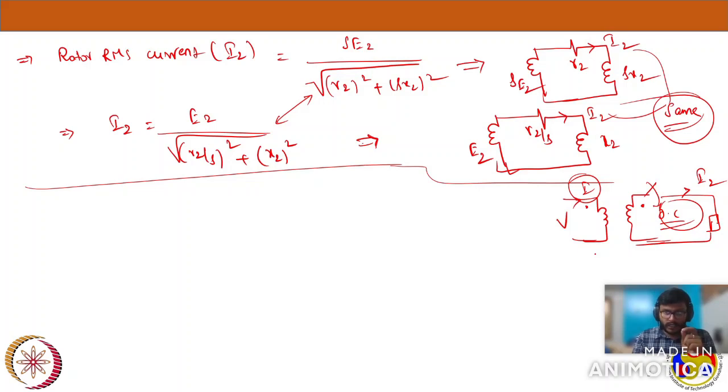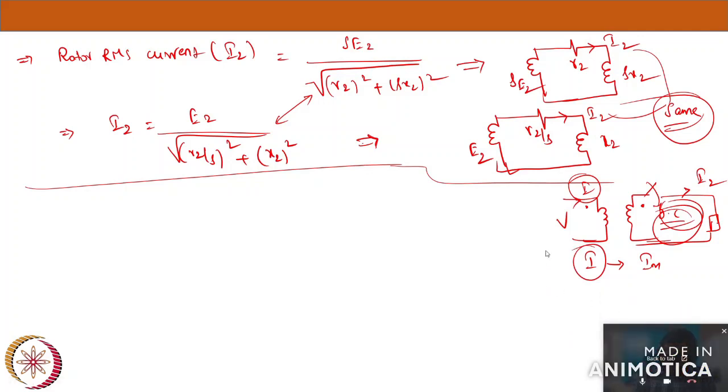in open circuit condition, when there is no current flowing in the secondary, the current required in that condition is only the magnetizing current. So the current drawn from the supply is I0 only. Now in the second condition, I connect some load across my secondary, and the current drawn by the secondary is I2 now.